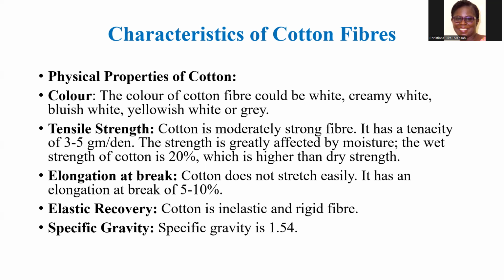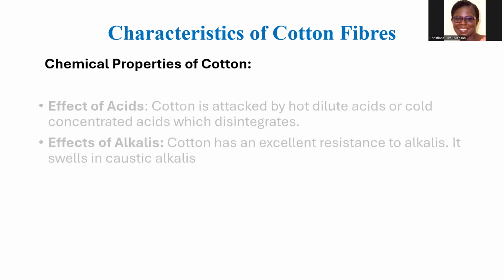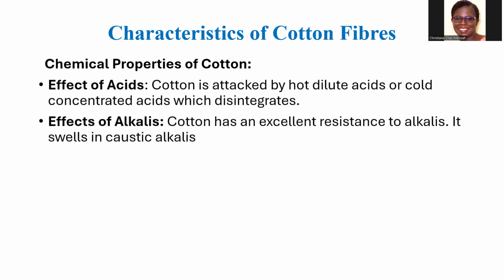Okay, so elongation at break. Cotton does not stretch easily, so it is inelastic. It has an elongation at break between 5 to 10%. When you stretch it a small amount, you force it, it will break. Elastic recovery: cotton is inelastic and a very rigid fiber. The specific gravity is 1.54. So let's look at the chemical properties of cotton.